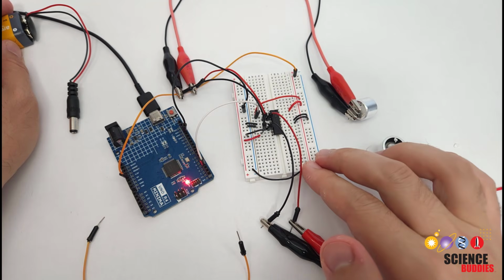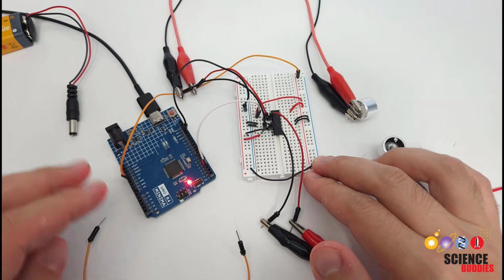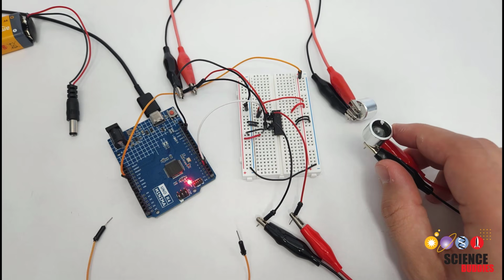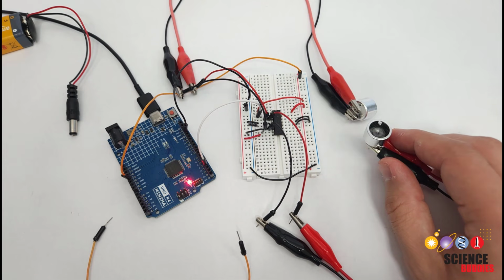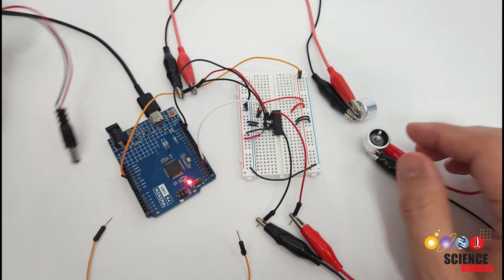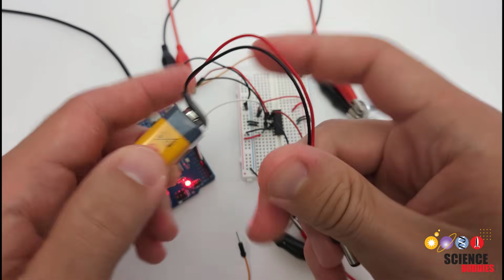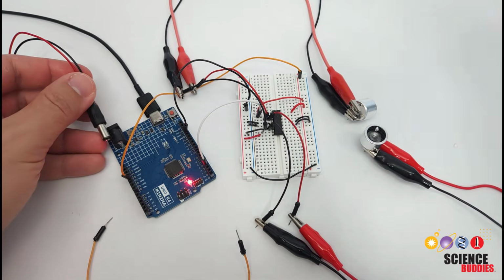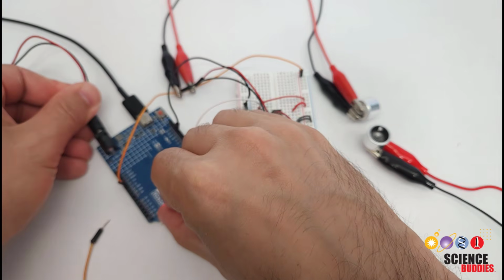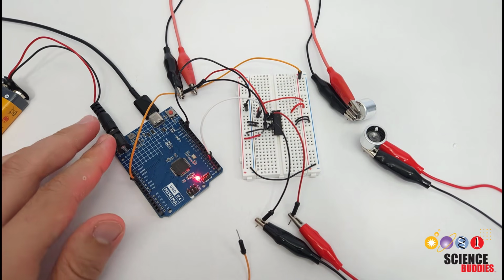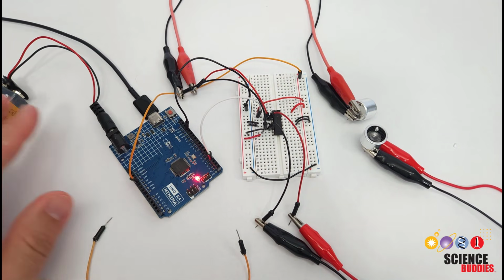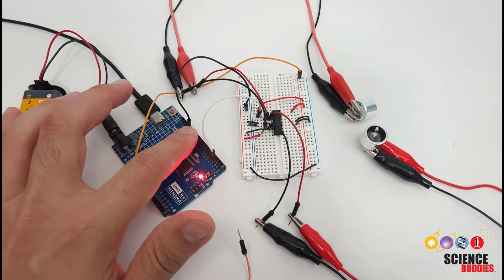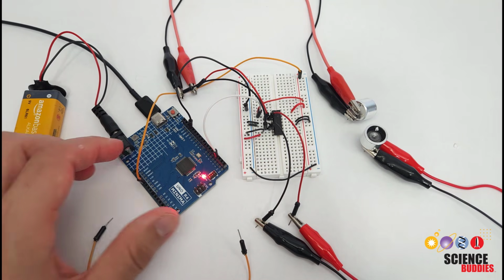Now we're going to switch back over to the camera because this is something I couldn't show as well in Tinkercad. Remember, we talked about how the H-bridge is going to allow us to drive our transducers or transmitters with a higher voltage power supply, but we haven't connected that power supply yet. So here I have a 9-volt battery with a snap connector and a barrel plug on one end that's going to fit into the barrel jack on the Arduino, and that allows the Arduino to provide a higher voltage to the circuit. Now, the Arduino has something on board called a voltage regulator that converts this higher voltage power supply to 5 volts, which is still used by all of the Arduino's input-output pins and the 5-volt pin.